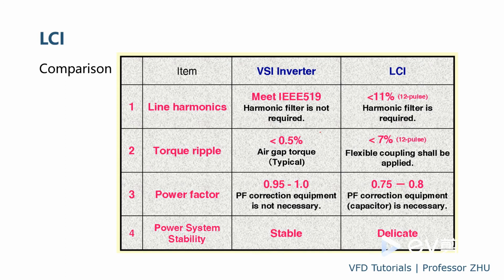And here's some comparison between the VSI and the LCI. LCI actually is an older technology and is used very little today. A few applications still use LCI, such as a huge drive for the pump or blower system, especially for soft starting. Like on the blower for the steel mill, the drive is only used to start the motor, and after start, it will be synchronized to the grid and run by the grid.